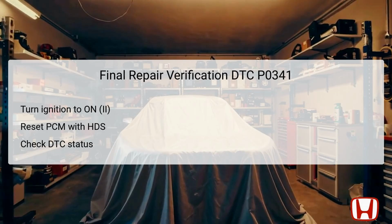After conducting these procedures, test drive the vehicle again under the prescribed conditions of 19 to 38 miles per hour for 10 minutes. Lastly, monitor the OBD status for DTC P0341 within the HDS. If the code indicates passed, it affirms that the issue has been resolved. However, if failed or not completed appears, further diagnostics will be necessary.